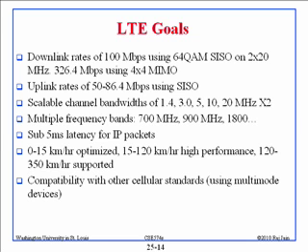Right? Now, to overcome that, what we do is we make every symbol longer. So instead of having a symbol which was 1 microsecond long, we make it 1.2 microsecond long, and the 0.2 microsecond at the beginning is the same as the 0.2 microsecond at the end. That is called cyclic prefix, because what we have done is we have taken the end, the tail, and put it in the front. So if there is any overlap, if somebody runs over it, no big deal, I still have another copy. Right? So cyclic prefix fixes multipath, and that is fixed, by the way.